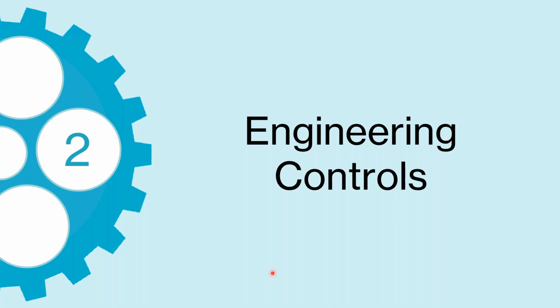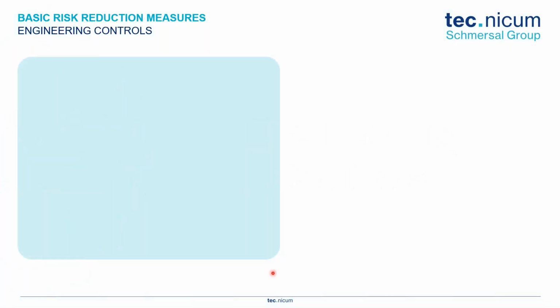And again, what are we doing with those hazards that we've identified as we try to apply these engineering controls? So with that, if we go back to our ANSI B11.0, it says, if we are looking at a machine, and we can't substitute, we can't eliminate, especially for these machines that we already have. They've been designed, they've been installed, and in some cases, they've been installed for 20 years, right? We can't eliminate the hazard, we can't substitute the hazard. So let's see what we can do to minimize exposure to these hazards.